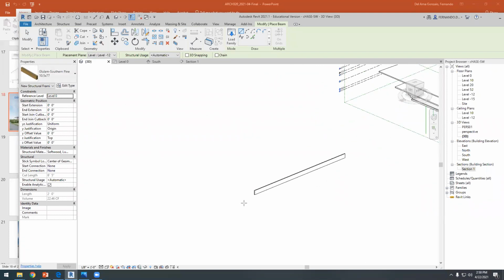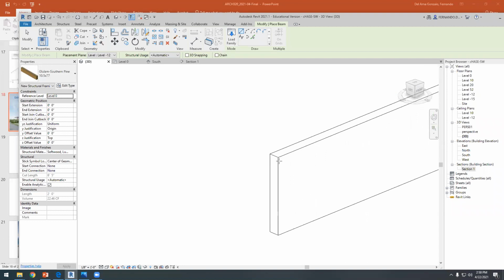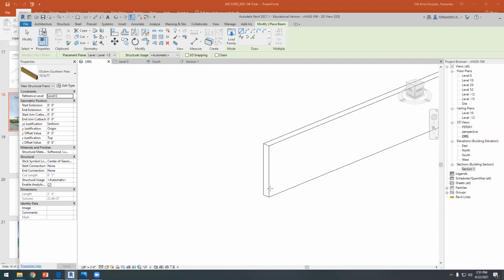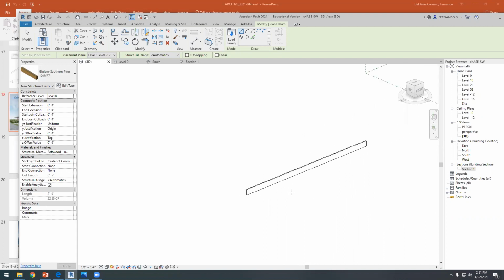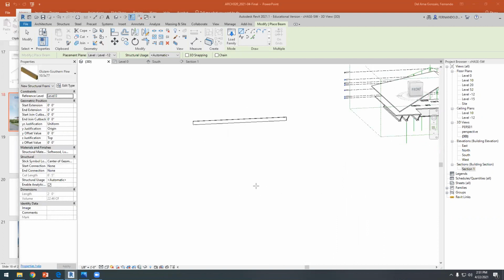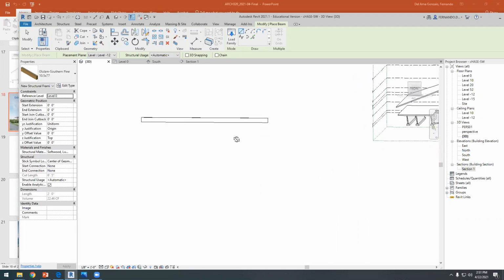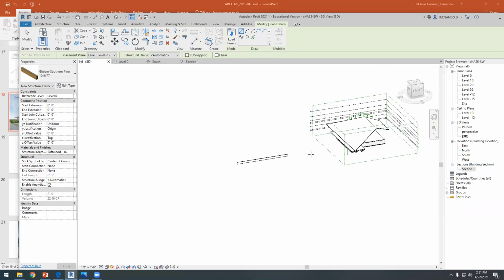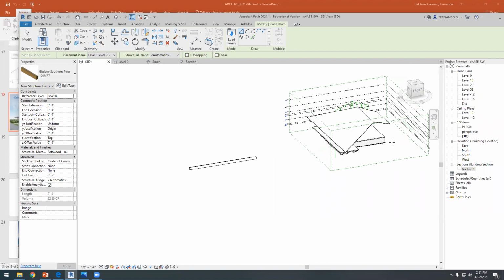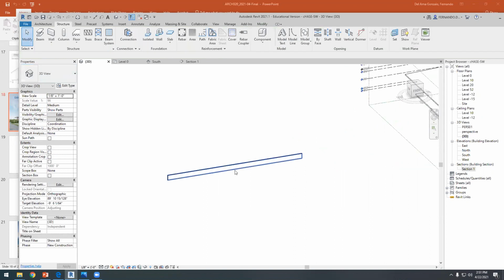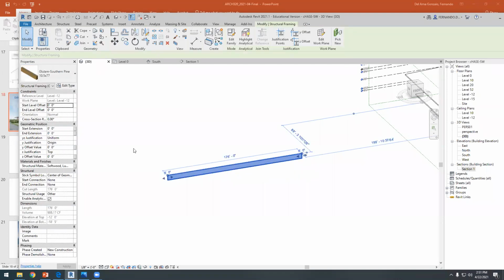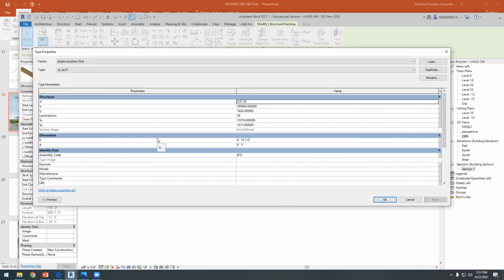Okay, so it's an element where the thickness is 10 inches, and the height is 77 inches. Does it make any sense? Well, maybe there might be elements with this kind of dimension, but you can go back and insert the element that you want, or we can edit type. I think it's better because the other table is overwhelming. So I'm going to select this one. I'm going to edit type, and I think I'm going to duplicate, and this is 10.5 times 77.